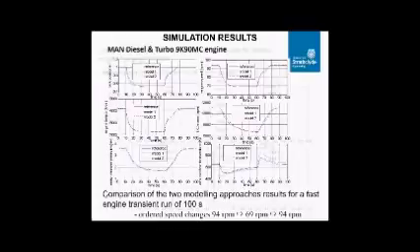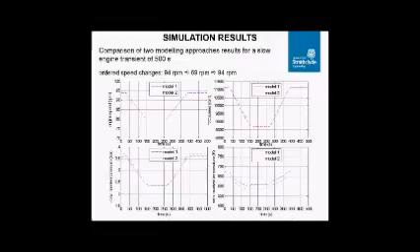In the next case study, we have again a two-stroke marine diesel engine, which was simulated using, again, both approaches of the mean model. The comparison of approaches is on slower engine transient runs of 1200 seconds with speed changes. It is obvious that in cases of slow transients, which are usual for ship propulsion plant operations, the engine operating parameters are also predicted with sufficient accuracy using the first approach.